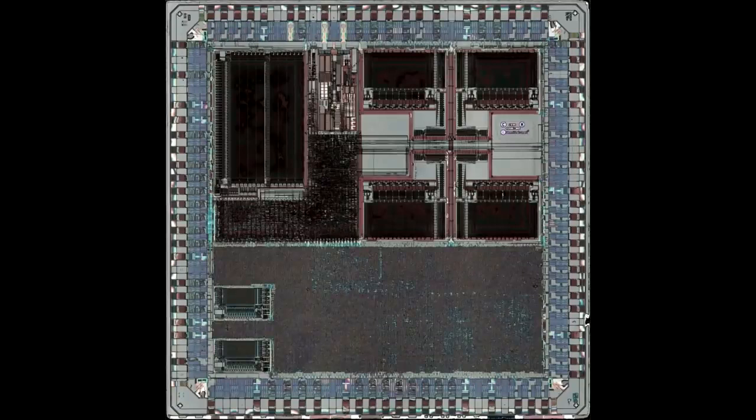I was interested in finding how the bits were encoded in ROM, so I continued delayering the chip. This was another dip in the Wink, and another metal layer has been removed. Bits in the ROM were not visible yet, so I continued the delayering process. At this point, we're starting to see more of the visual effects from the uneven etching, but it's still not too bad.